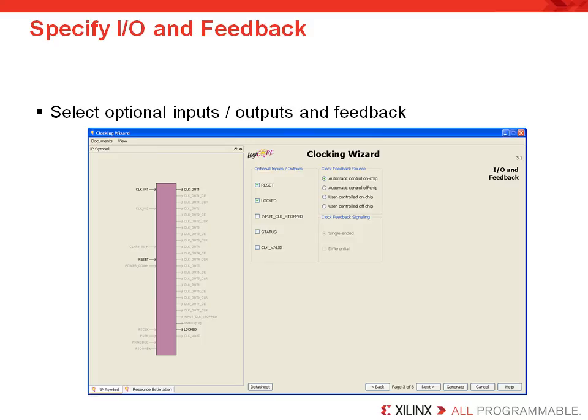You also have the ability to customize how the feedback of the output clock is routed to the input of the selected MMCM. This is important if you want to generate multiple clocks that are derived from the same MMCM and need to be synchronized.